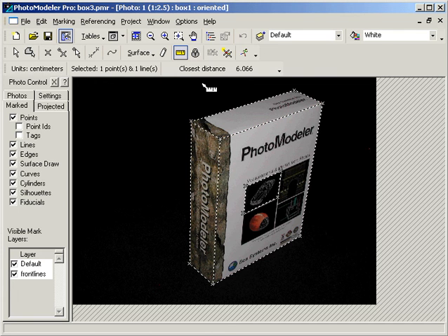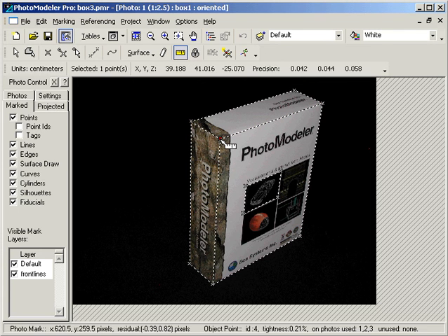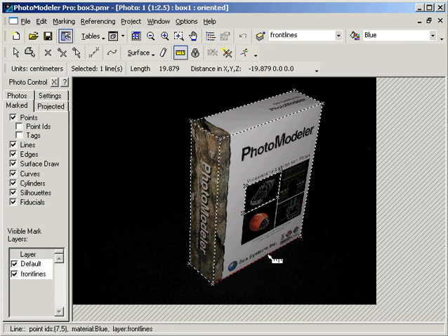The status bar also provides information about objects that are selected, whether using Measure Mode or Select Mode. If we select a point, the status bar displays its XY position, its residual, its point ID, its tightness percentage, and the photos it appears on. If we select a line, the status bar displays which points the line is connected to, its material, and its layer.